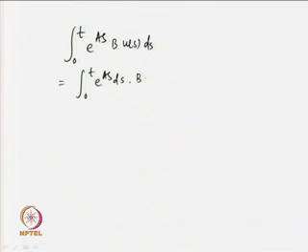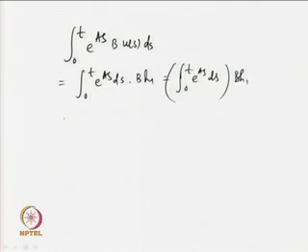The input to the system is h1. So, in place of u(s), allow me to write h1, thus giving us B h1. So, I have the integral from 0 to t of e to the power As ds times B h1. Now, when the integral is found, finally we get A inverse e to the power As with the limits 0 to t times B h1.